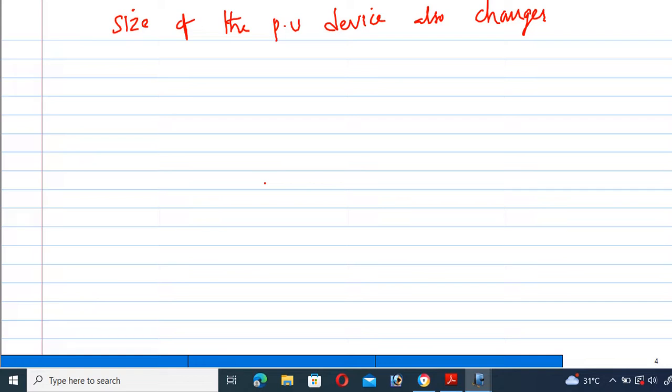Moreover, delay increases in direct proportion to the number of inputs. If each pull-down transistor is kept minimum size, then each will represent one gate capacitance at the input, and the resistances of the pull-down transistors will be in series. Therefore, an n-input NAND gate will have n times the delay of the inverter.